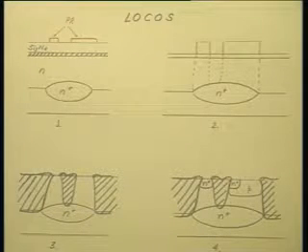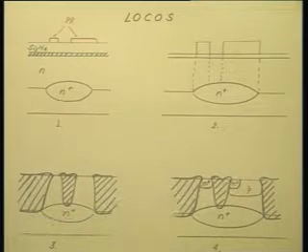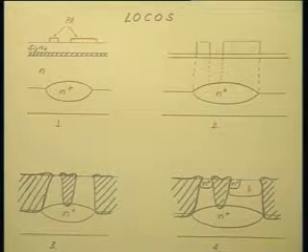There is no question of having the base separated by 20 micron or whatever distance as in the junction isolation case. The base now can occupy the entire region in between the two oxides, which means a tremendous improvement in the packing density. Okay. Same thing is for emitter also.